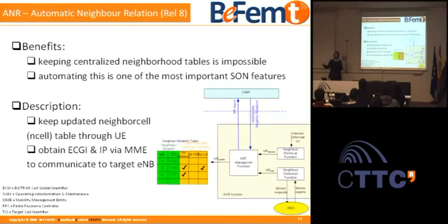So you start using the mobile phone to do this business for you, because that mobile phone, which is placed in a mutual coverage area, is able to see you and is able to see your neighbor. Therefore, there are all the protocols in place which allow you essentially to discover your neighborhood via the mobile phone. You then piggyback that to the operational management, and it will tell you whether this is a base station which you're not allowed to remove from your table, a base station which you're not allowed to do a handover to. It might also be a base station which has different features.